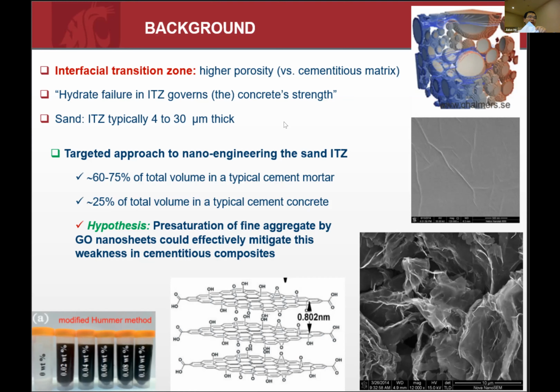On its surface, you've got a lot of chemical groups, carboxyls, hydroxyls, epoxy, and so on. They're highly reactive because of the nano effect, and cement particles will be adsorbed onto it. For people less familiar with nanotechnology, we're not talking about a nanofiller here. It's truly a nanoscale catalyst, which will regulate and catalyze the hydration process of cement.